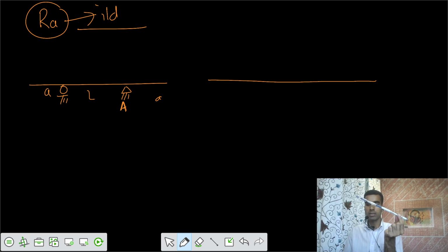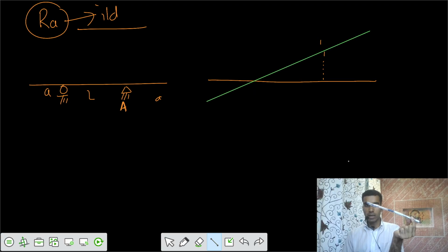So this is our profile. Once you apply a unit displacement of 1 here, the profile would be in this fashion. But you have to ensure that the other support is intact. Where it touches, that is the location of the support. Let's say this is support B. That means when the load was at B, your reaction at A is 0. So this is our profile.